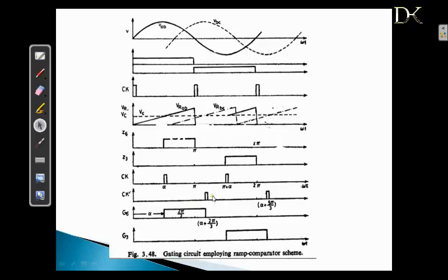Each pulse sets a flip-flop. These flip-flops are cleared by two clock pulses, clock bar, obtained from another channel using the appropriate line voltage. The clock pulse and clock bar are also used to produce gate pulses for another pair of thyristors. Pulses G6 and G3 are produced considering the synchronizing line voltage VAB.